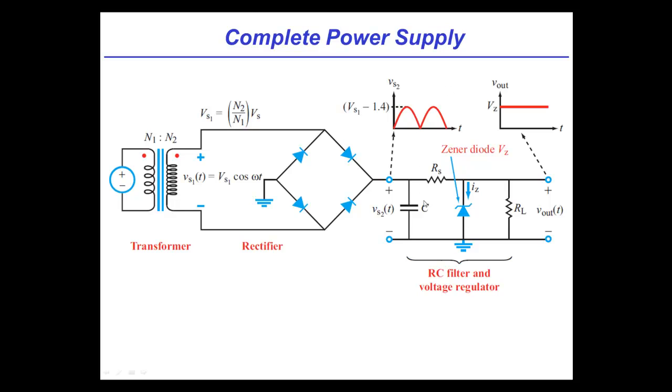Okay. Anyway, so we actually use something that does exactly that. What we do is after that filter, we put in something called a Zener diode. Oh, so here you reproduce the whole circuit, actually. Right. I put it all together. Okay. So I put the Zener diode here. And what the Zener diode does is it's exactly what I said. It's basically a cutoff. Think of it for the purposes of this class as a cutoff circuit. Any voltage, any electrons, any power associated with voltages above the cutoff of this Zener diode will get shunted out and burnt off as heat.